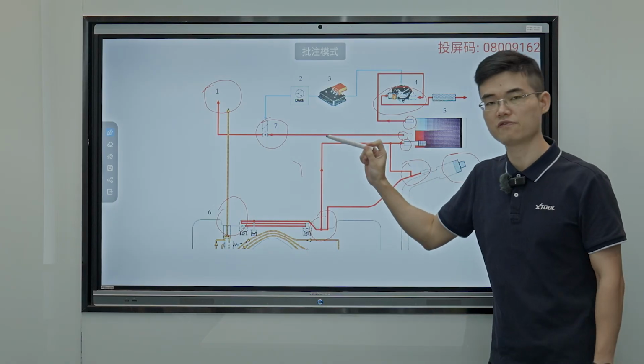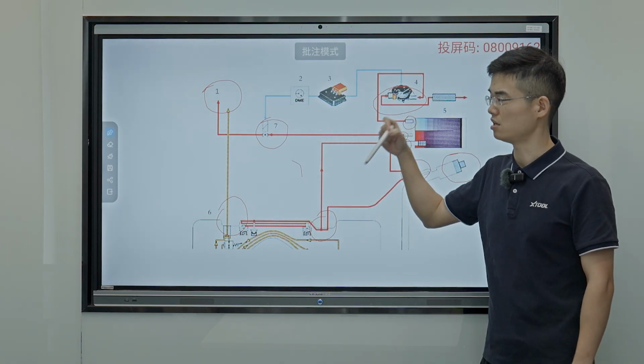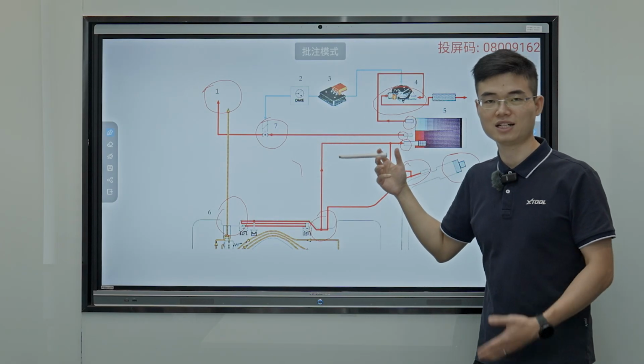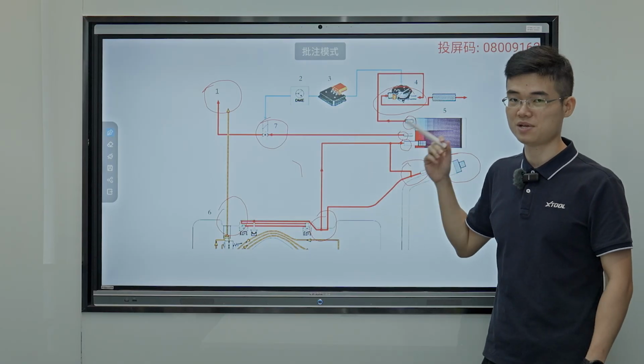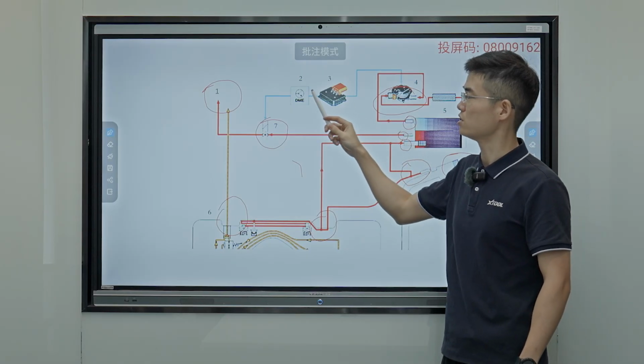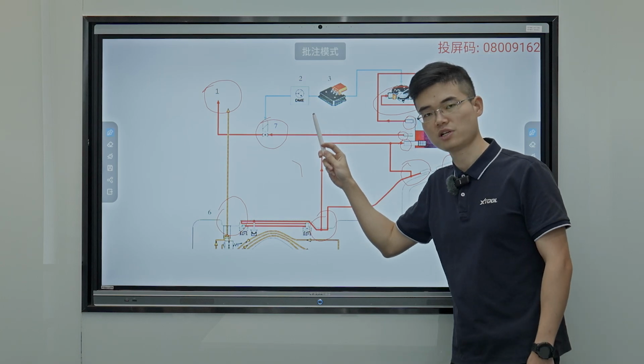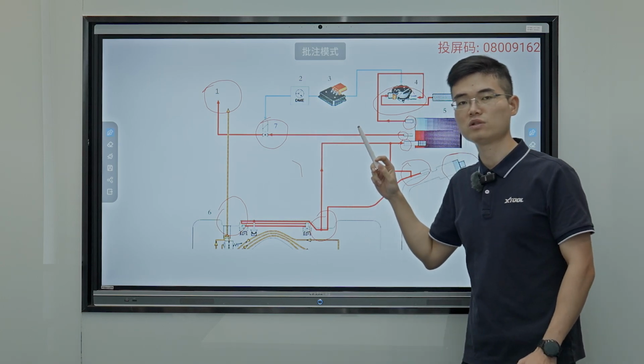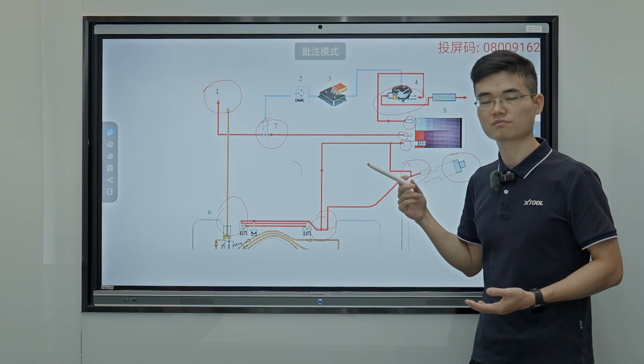If none of the joints can be detected with any leakage, it means maybe a malfunction of the digital motor electronics. That means we need to upgrade the software.